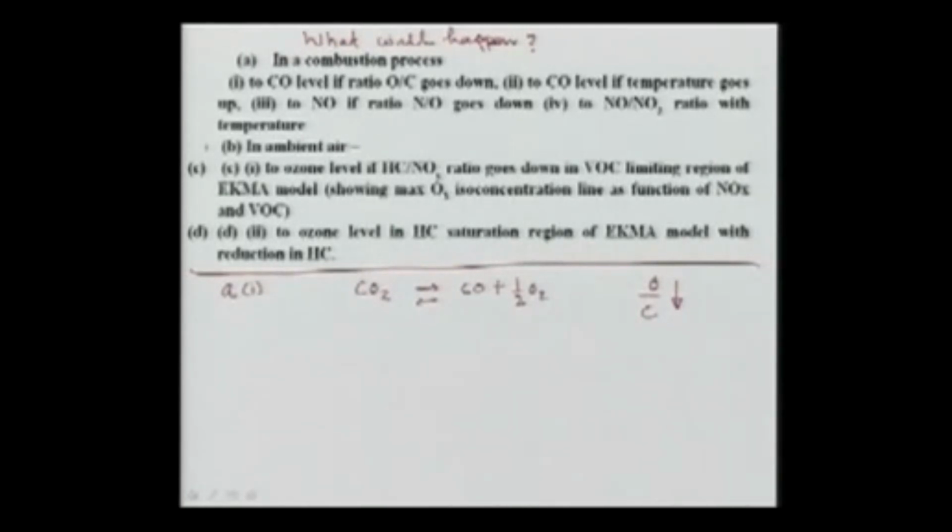If my oxygen becomes less and less, then, because the combustion will not be complete, my carbon monoxide will go up. Okay, so CO will rise.